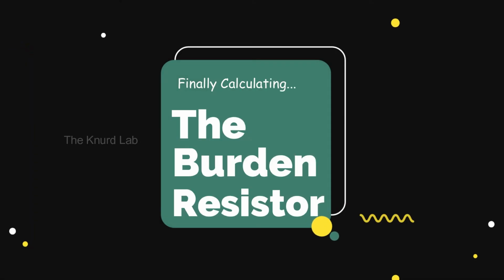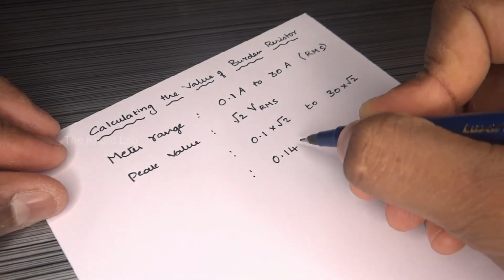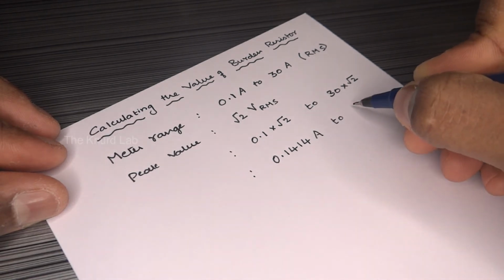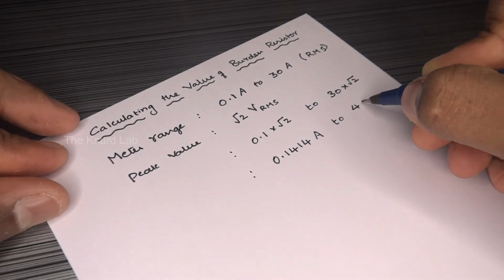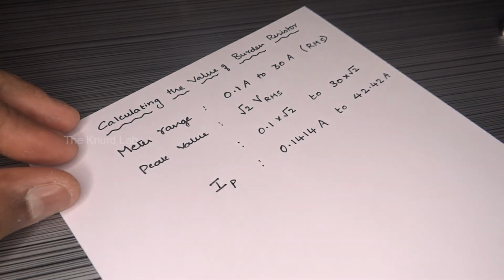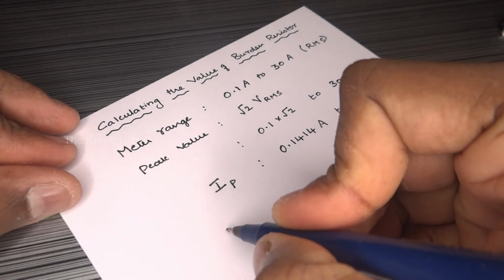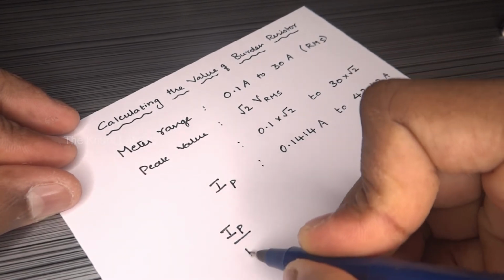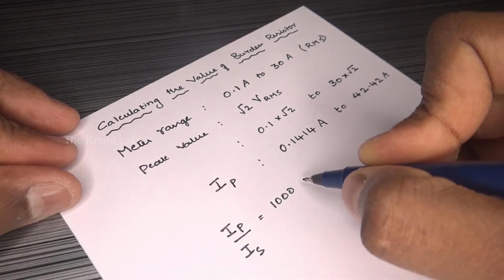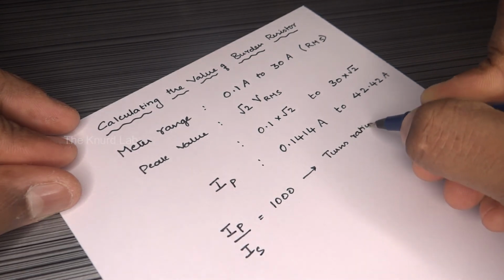Finally, let's arrive at an optimum value for a burden resistor. Let's say a current measurement range is between 0.1 amperes and 30 amperes RMS. Though a target range is between 0.1 and 30 ampere RMS, a current transformer always sees instantaneous values of currents through it. So it's important that we design a burden resistor such that it can handle voltages corresponding to the peak value of the current that we intend to measure. This we can calculate easily because the peak value of the current is root 2 times its RMS value. So our design must be such that our ADC can handle voltages corresponding to currents between 141.4 milliamps to 42.42 amps in the primary circuit.